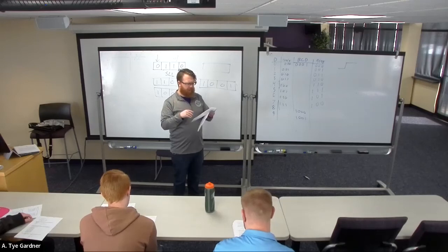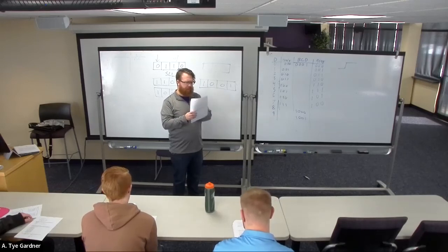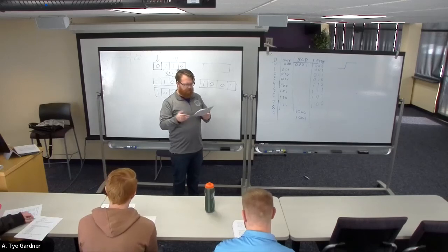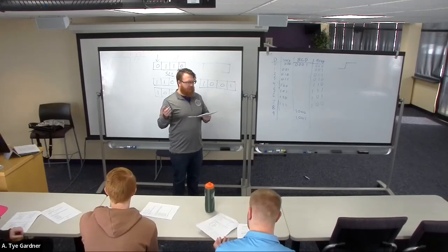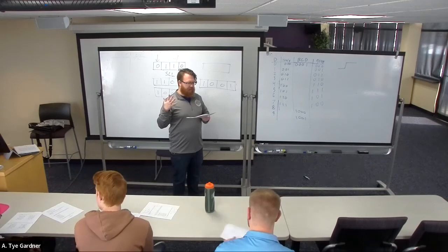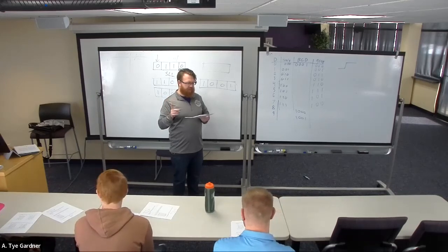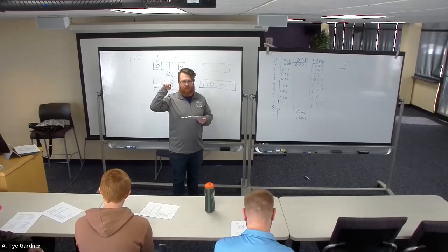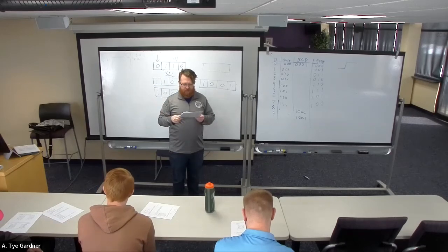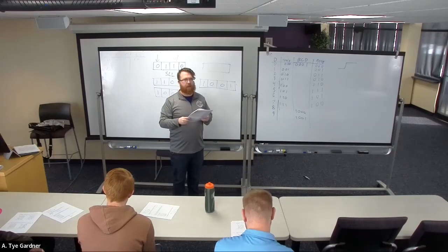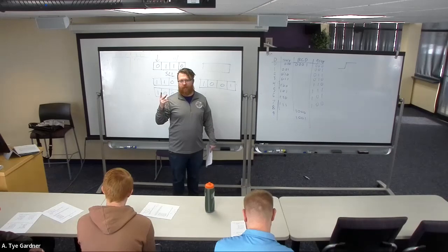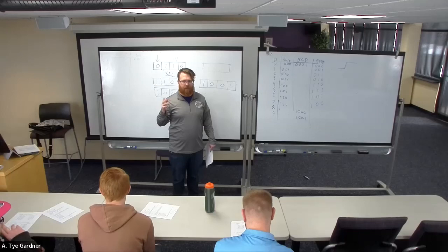Part A on that, I think everybody got right. So good job, at least on that. For the K-maps, the most common problem was in number 5A: a lot of you didn't catch that there were the 4 corners that you could use to simplify further than using just a 2 input. So that would have been a minor error. And on problem 6, it was much more common. The issue was you failed to flip the not bars as you're supposed to with the product of sums. That was the most common problem.